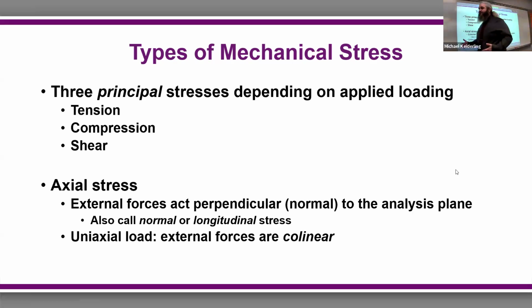And then lastly, there is shear. Shear is sort of side-to-side sliding stress. That's a stress where the force, instead of being perpendicular to the plane that cuts through, is parallel to it. So if I had a cylinder of some sort, when I'm pulling on it, it's tension. If I'm pushing it in, it's compression. With shear, I would be moving one side up and the other side down.